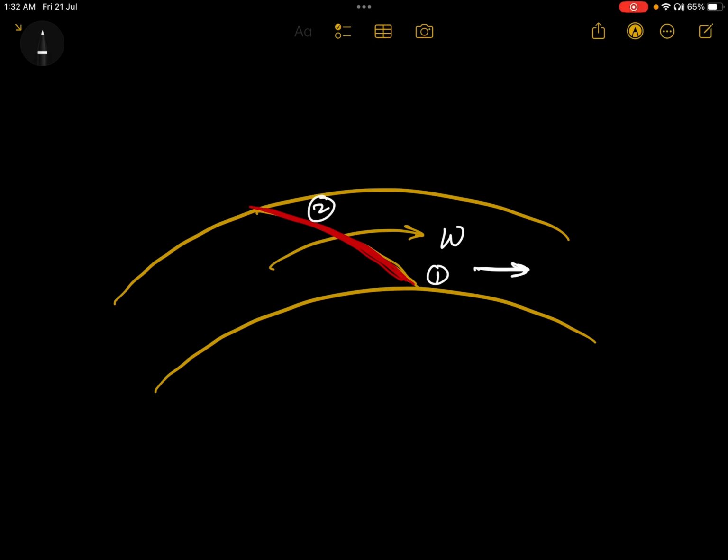We have to take the tangential velocity, that is u. Okay, so first at the inlet we want to draw the velocity diagram. First of all, draw the relative velocity, because the relative velocity is always tangential to the plate. So we'll draw the velocity tangential to the plate, and because it is entering, it will be VR1.